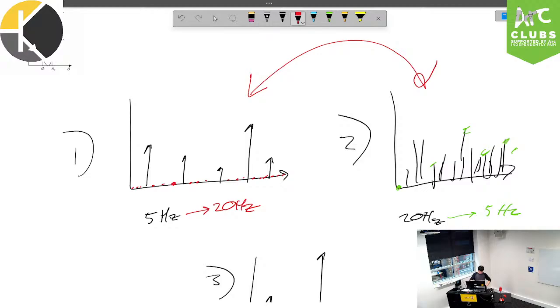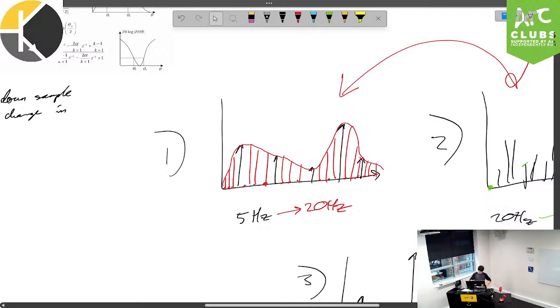We would want some manner of low-pass filter or frequency response to recognize that this is the manner of shape we want the signal to take, right? And if this is the manner of signal we want it to take, we need to raise those points as such. Now, there are a couple ways we could do this. The first way would be through windowing, where we go ahead and perform an averaging window.